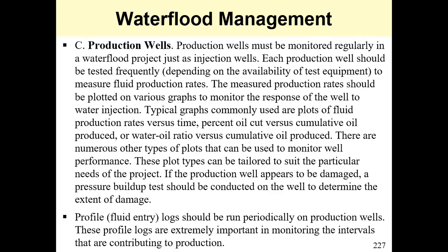So you will also monitor your production wells. They need to be tested frequently. There are several tests you could use. The build-up test comes to mind in determining whether there is damage and what the extent of the damage is. You could also run profile logs.